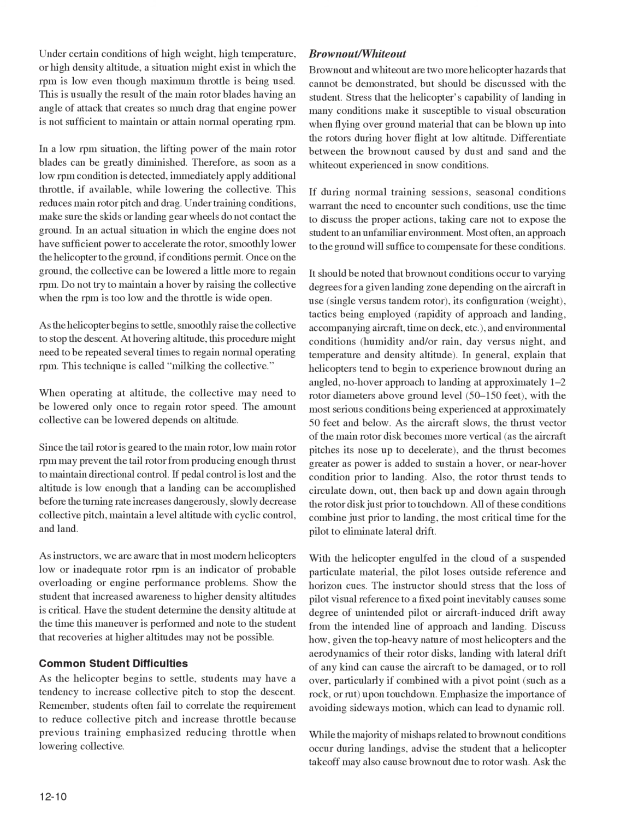The instructor should stress that the loss of pilot visual reference to a fixed point inevitably causes some degree of unintended pilot or aircraft-induced drift away from the intended line of approach and landing. Discuss how, given the top-heavy nature of most helicopters and the aerodynamics of their rotor discs, landing with lateral drift of any kind can cause the aircraft to be damaged, or to roll over, particularly if combined with a pivot point, such as a rock or rut, upon touchdown. Emphasize the importance of avoiding sideways motion, which can lead to dynamic roll.